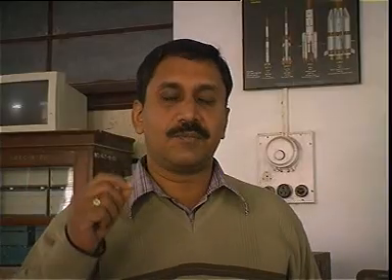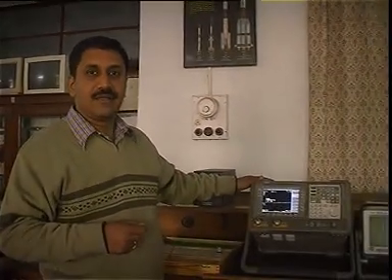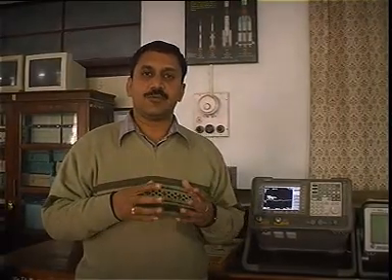Supposing I am interested in the spectral content of the signal. What will I do? I'll actually mathematically calculate the Fourier transform of this. The Fourier transform is a tool which takes me from time domain to frequency domain. So I multiply x(t) by e^(-jωt) dt, integrate over minus infinity to plus infinity, which gives me X(ω). That X(ω) is what is being represented by the spectrum analyzer. So X(ω) is nothing but the spectrum of x(t), the spectral content of x(t). That is what we are interested in.